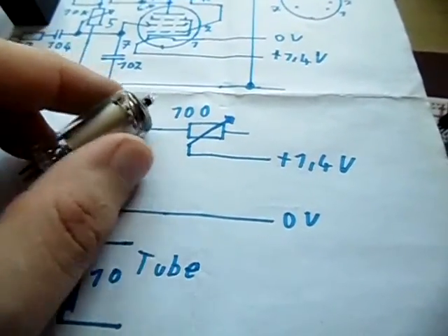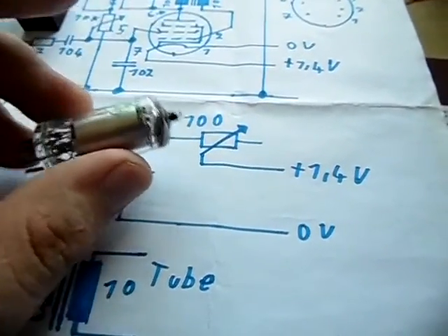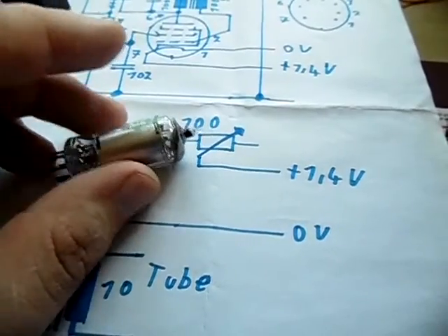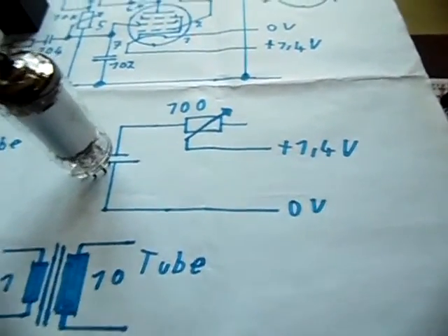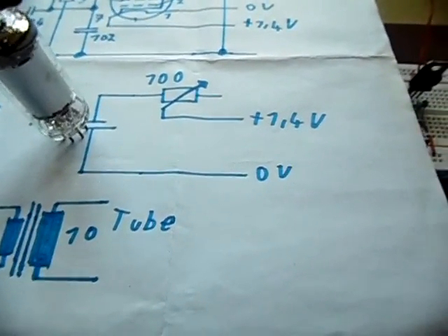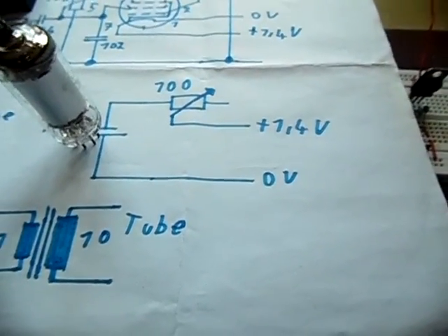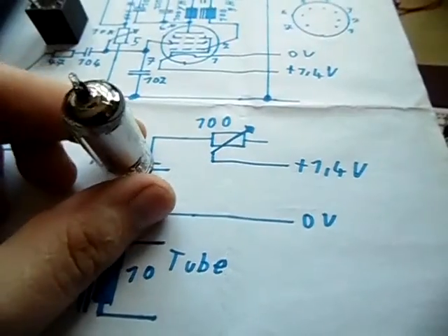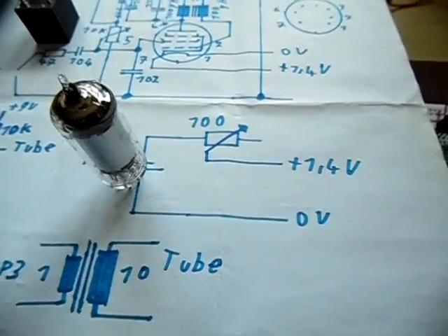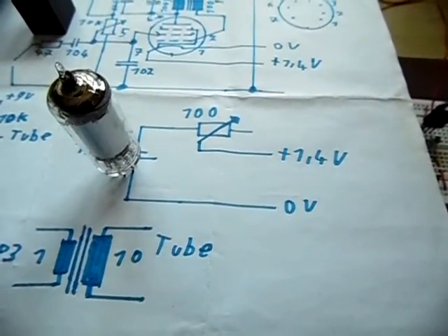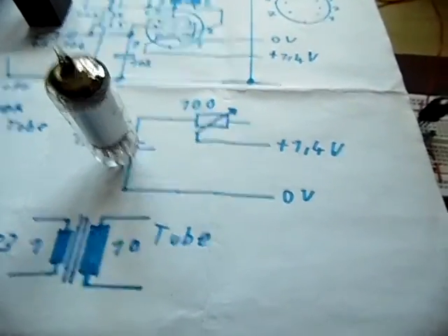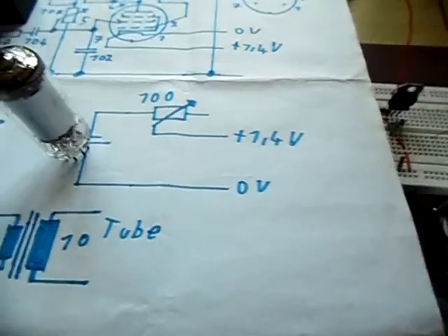Well, I do have a lot more tubes than this one, but there's a problem with these tubes, and this is the high voltage. So meanwhile you can make a transistor circuit with like a 9-volt battery or 1.2 volt battery. These tubes will require like 200 volts or 300 volts or some even more. So it's very dangerous for beginners if you work with these high voltages and want to make a tube transmitter.